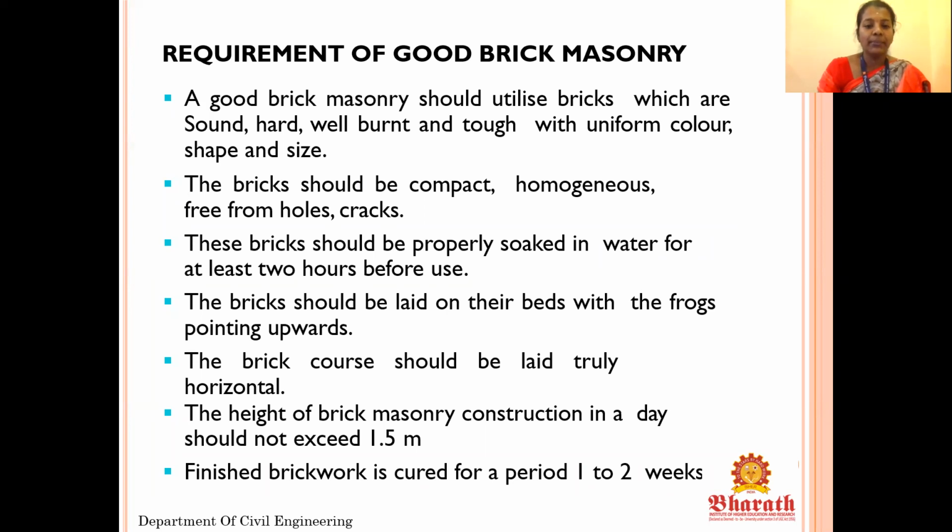The height of brick masonry construction in a day should not exceed 1.5 meters, that is around 4 to 4.5 feet. Finished brickwork is cured for a period of 1 to 2 weeks. The curing is a very important thing, because after the construction, after everything, including painting, is over, it's the curing period.